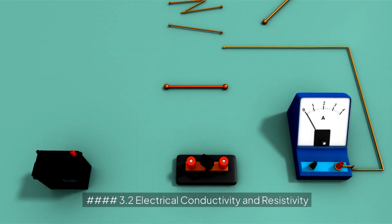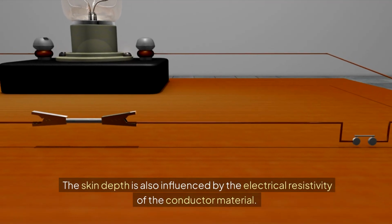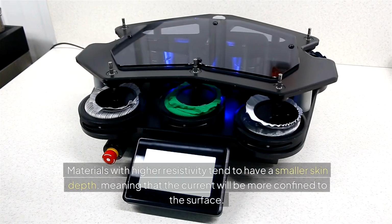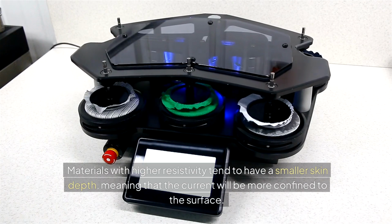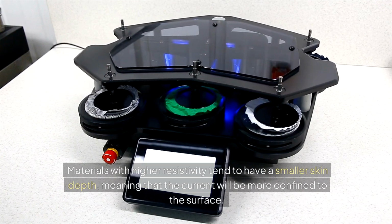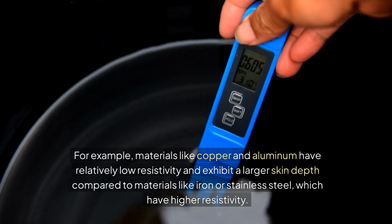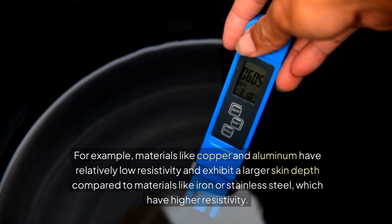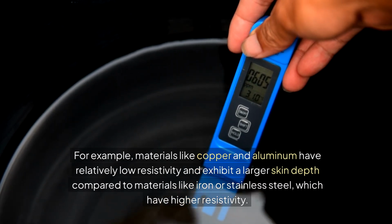Number 3.2 Electrical conductivity and resistivity. The skin depth is also influenced by the electrical resistivity of the conductor material. Materials with higher resistivity tend to have a smaller skin depth, meaning that the current will be more confined to the surface. For example, materials like copper and aluminium have relatively low resistivity and exhibit a larger skin depth compared to materials like iron or stainless steel, which have higher resistivity.